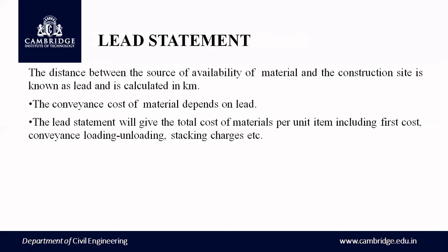For that, we need to search for a source of gravel, and the distance should be calculated in kilometers. The distance from the source, it may be a quarry, to the dam site is called lead, expressed in kilometers.